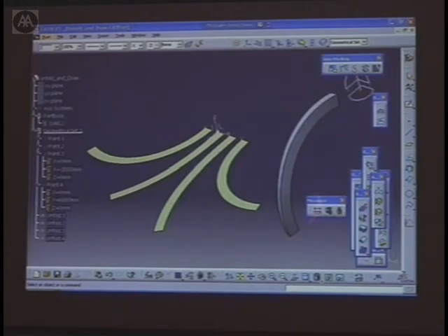So as you unwrap this thing, in this case, it's not like the developable surface before. This is like the inverse of a banana. You know that when you peel a banana and you put the banana peel on the table, you can try this at home, it's curvy and you can't really mush it down flat because it has a curvature to it. By the same token, there's a curvature here, but I'm going to build it out of flat steel plate that's coming off a rolled plate mill, and that I'm going to laser out into the shape, and then it's going to be bent and curved into this form, and then welded together. That means that while you're going through that curving, there is a deformation going on, and that deformation means that it's a deviation from the actual design intent.